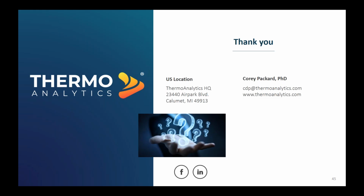That can be a constant value that's supplied, or something that varies over time. Furthermore, the view factors that are automatically calculated are going to figure out the solar apparent area of the satellite and how much solar loading the different elements of the model are going to receive, both direct from the sun as well as reflected off the earth. So there's a variety of ways that can be applied and considered.